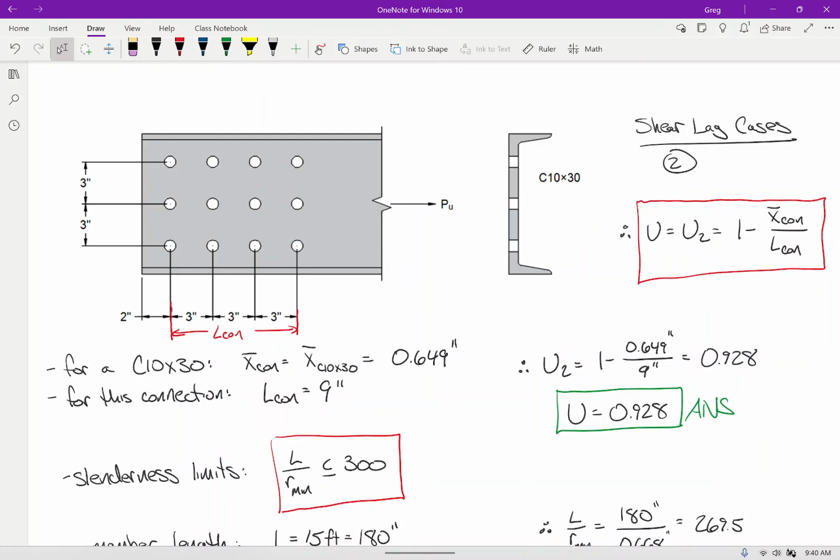As for the difference between case 1 and case 2, case 1 says all of the elements are connected. Case 2 says some of the elements are connected. And what I'm saying is there's no bolt through the flanges. So because there's no bolt here or here, some of the cross-sectional elements are connected, not all, and we're in case 2. That's a good question.